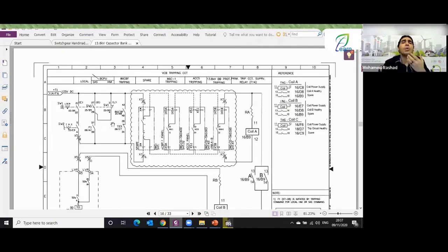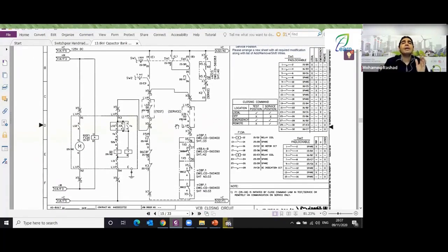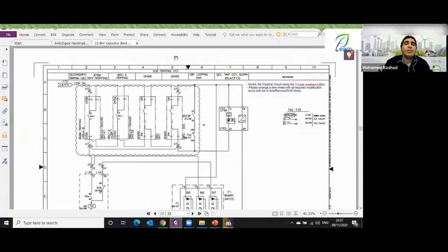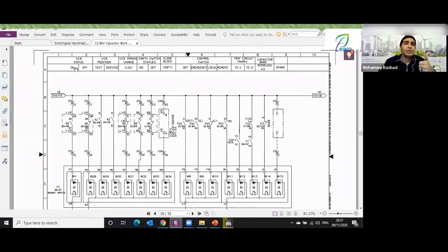You might say, all the things you mentioned are present here in the wiring. Here are the requirements of SEC, Aramco, and others. The same thing you did here with the wiring is like unknown variables inside the PLC itself. Even though the PLC is supposed to reduce this wiring process and save us effort, as a precaution I am doing duplication. What does duplication mean? It means the same thing I did with the wiring, I will do inside the PLC. That's why, engineers, you will find here the circuit breaker on and off state, the circuit breaker test state or service state, and whether the spring is charged or not. The same applies to the earth switch, which we will talk about tomorrow, whether it's on or off.